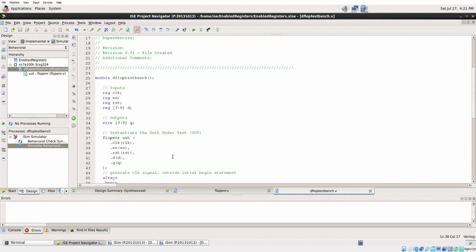I have provided the clock signal using the dot operator. When we use this dot operator, we directly assign the clock variable to the input. However, we can also write it like this. If you write the dot operator, it will not consider the argument's position, but will map it to the clock signal accordingly.